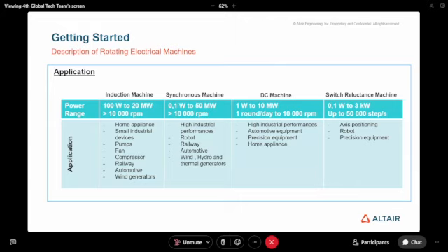As you can see here, radial laminations are laminated like this, and you can find the bridges. Whereas axial laminations are cut like this, and actually there are no bridges inside, and we need some mechanical fixation, like we have here with a screw or a sleeve or something like this.